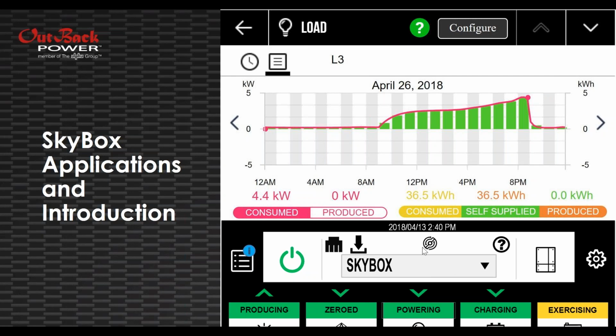And in the lower part of the window, we see the picture of SkyBox's home screen showing that it's been set up for non-export. So it's got zero power being sent back to the grid. And then we'll talk more about this in detail a little bit later, but that PV production is simultaneously powering those loads, charging the batteries, and we're supporting backup power. We've got a genset that is connected to the SkyBox and is ready to go in case of grid outage. So we're doing that self-consumption and we're supporting backup power.